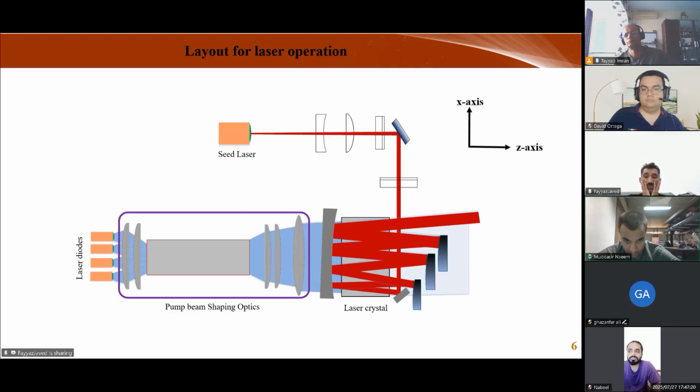We will see. That will be very nice. I will require the parameters, whatever you have, like the waveguide lens especially, and the laser diode information, or if you don't have it, you can give me the model. I will see what information I can extract and then we will see how we can simulate it. I think it is best simulated in sequential mode, which will be much better than non-sequential because it will give us a lot of flexibility to see vibration effects, PSF, MTF, a lot of things. And the system I am seeing here, I think I can simulate in sequential mode as well.